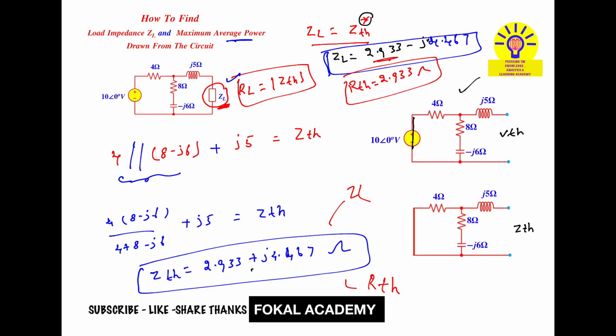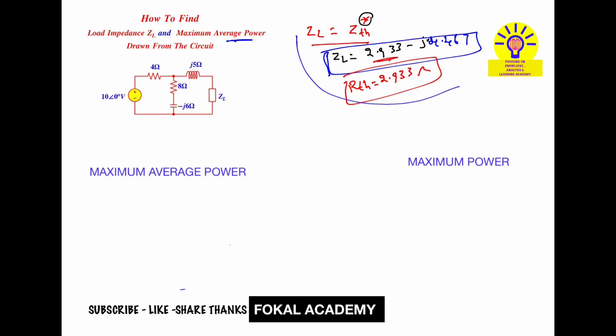In the next step, how to find the maximum average power. In some problems you find only maximum power, not average, so the two are different. One problem will be maximum average power, another is maximum power. Whenever maximum power is asked, the formula is Pmax equal to the magnitude of VTH squared by 4 RTH.